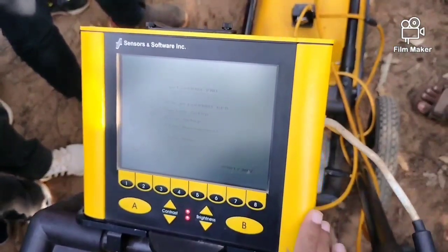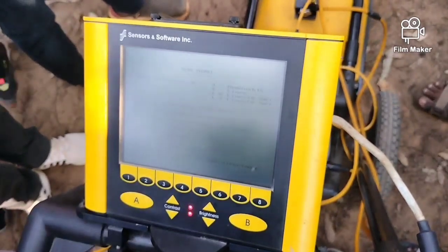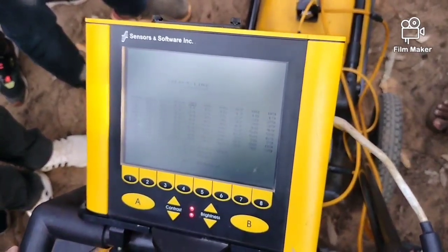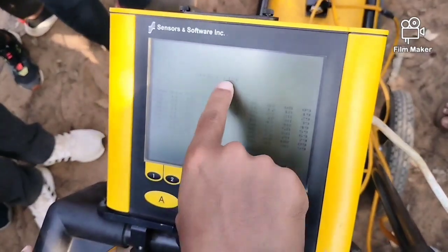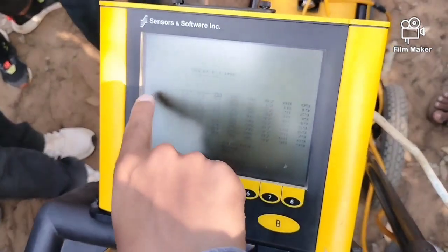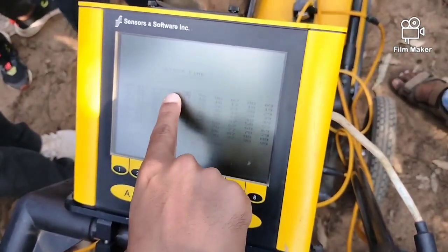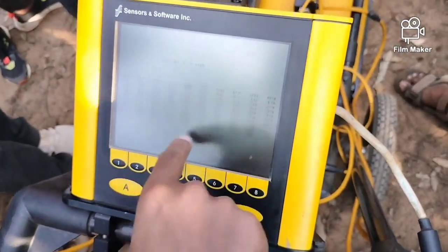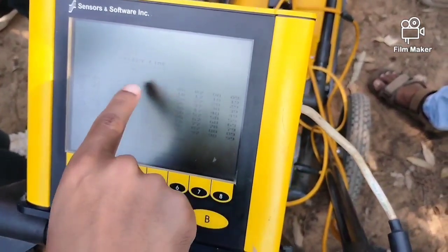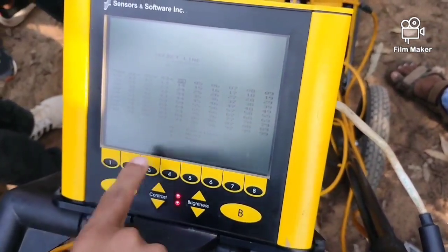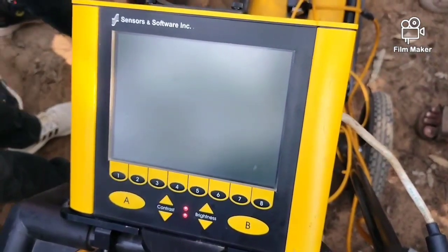Okay, now let's run the Pulse Echo GPR, collect line data, because we are moving along a line direction. Then it will show you the directory number. This is select line number. We've already taken line 00, line 01, line 02, line 03. That's why you can see a star. These files are still available to take data, so you can take data in 04, 05. We'll just press 1, which is for run. And now you're good to get the data.